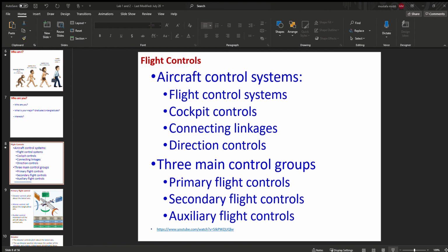Okay, which means that your camber is gonna be decreased, and with the decreased camber, you're gonna get decreased lift. We will have the opposite mechanism on the other side. Actually, you're going to increase the camber on the left side, and you're going to have higher lift. Okay, this is what we discussed. What's going to happen is that your airplane, because of the force balance, you have higher force on the left wing, which is going to push your aircraft to roll right, essentially. So the force balance is going to be disturbed.